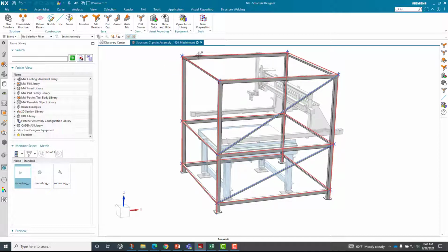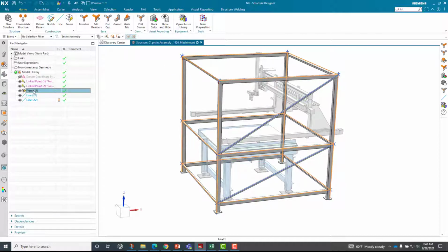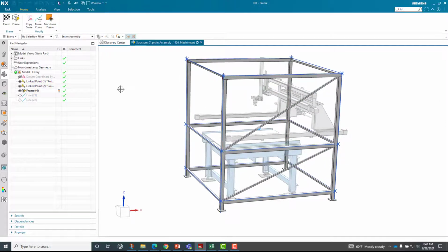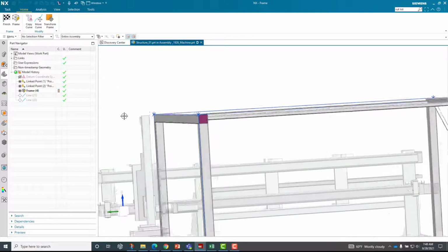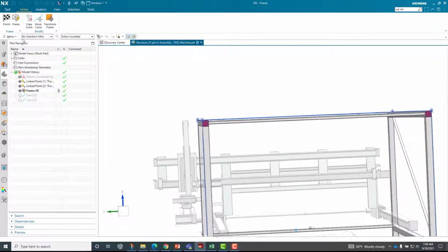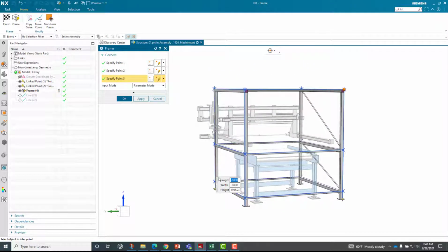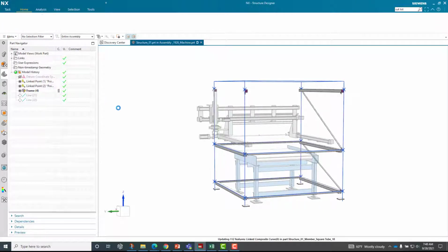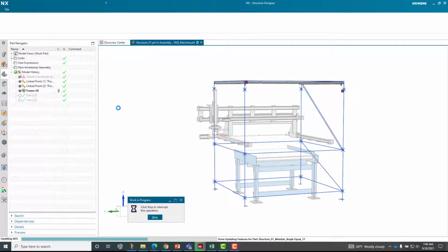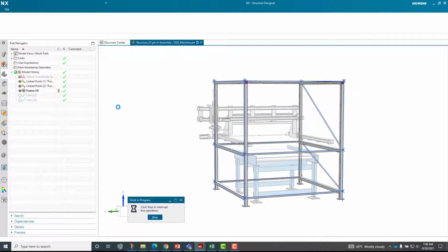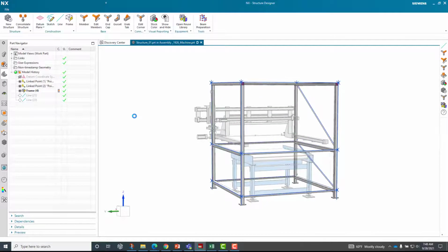Even just taking, let's say, the skeleton. That's just this frame piece, and if we wanted to adjust that, because looking at it, I'm going to have a pretty wicked collision right there. It's no problem, because remember, I'm defining the points. So I've got point 1, point 2, point 3, that's the height. It's currently at 1955. I just snapped off of a point. Maybe I'll take it to 2100. Let's see if everything updates. So far, so good. And voila.